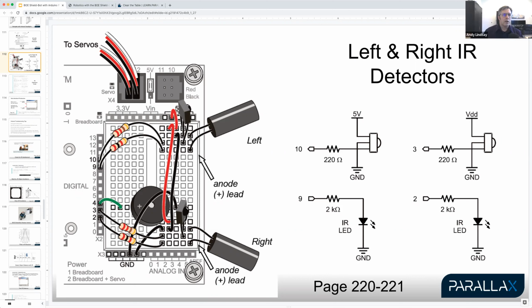Okay. So what we want to do is check to make sure that the jumper wire from 5 volts is on the top row, as is your top pin for the receiver. Yep. Okay, now go down to ground and follow your ground wire. Your ground wire should come up to the lower infrared receiver and go to its middle pin. And then from the middle pin row, another jumper wire goes up to the middle pin row of the upper IR receiver. Okay.